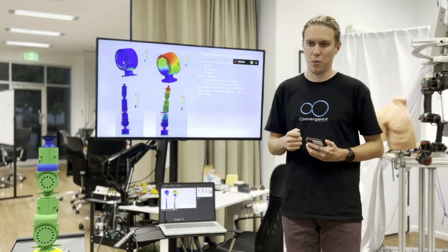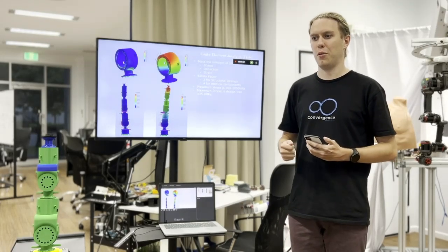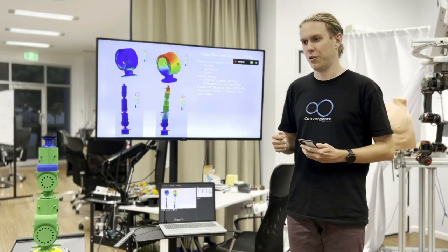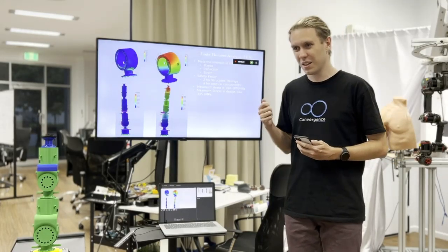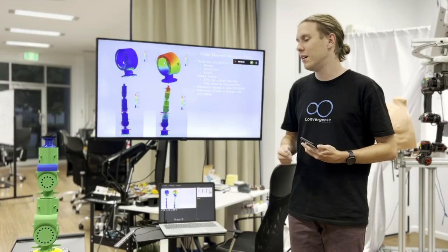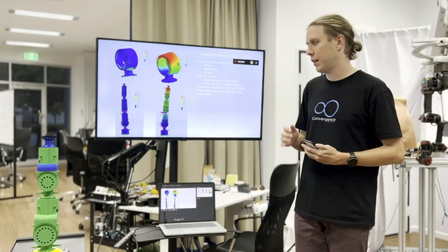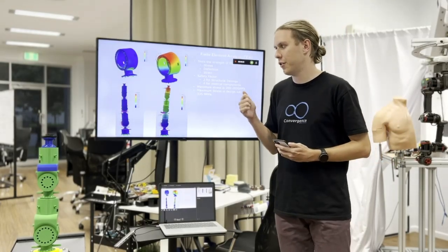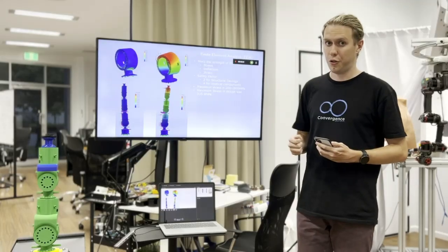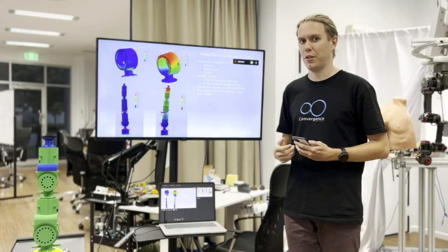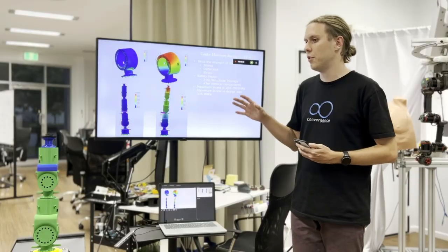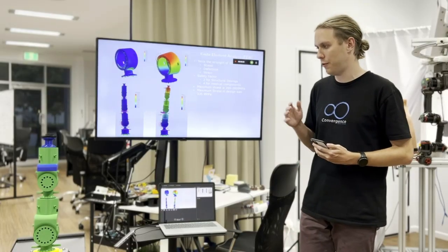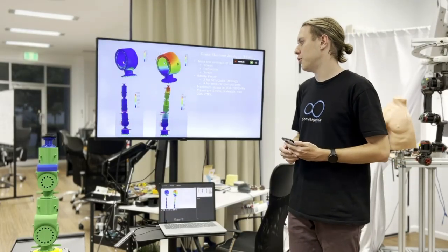The other important part of this was that I used a safety factor. Safety factors are important because they make sure that even if we double the worst possible outcome for a certain thing to happen, then we don't have to worry about it. It's made to be very safe. So for structural designs such as this one, I just use 2. If we were to do medical designs and stuff like that, we'd actually use 4. But because this is just fully structural, we only had to use 2.